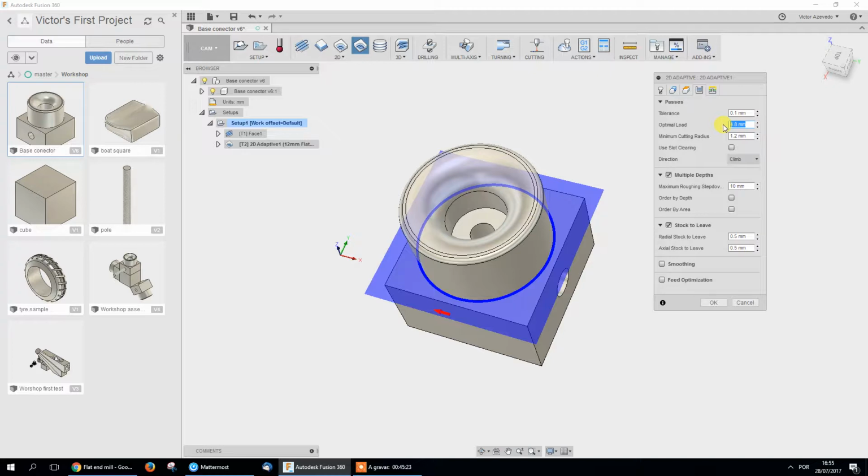As you remember from that design I made on the board, the diameter of the tool and the step over is how much you're overlapping the tool. We're going to set it up as 0.5 millimeters. From a 12 millimeter tool, well, let's put 1, it's faster. 1 millimeter of the 12 millimeter tool.